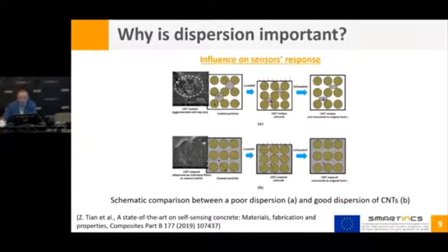This will be a problem, of course, because you will see, for example, as soon as the load will be applied again, you should see a progressive drift in the signal base of your material. So this is, of course, something not so good to see in a sensing system, because you would like that the system recovers the initial resistance or impedance value after the load has been removed. In this case, this cannot happen, because once these bundles have been deformed, they won't recover their initial size.